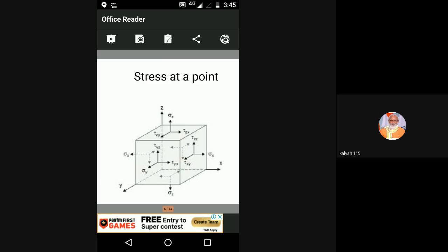Okay, like that. So to represent the stress, we may ask one question: the stress is developed on which plane, in which direction? That is very important. Suppose I simply call the stress value 50 megapascals, but immediately we may get a doubt: these 50 megapascals are developed in which plane, in which direction? Otherwise, there is no meaning.